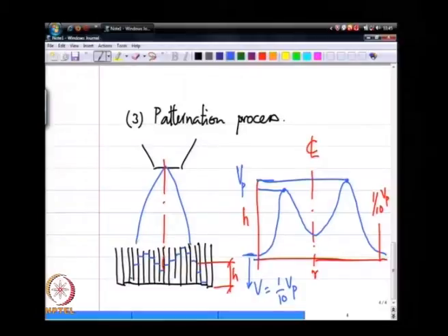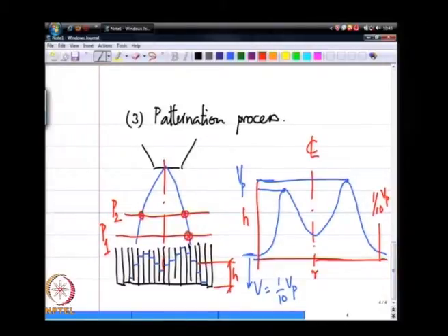So, once I know this, I can essentially do what we did with the image. So, I get a pattern at one axial location, pattern at another axial location, and from that, knowing the spray edge at the two axial locations and knowing the origin of the spray, I can fit a second order curve to these 3 points, and from that calculate a spray angle.